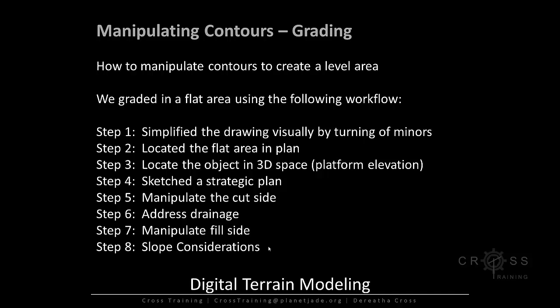So we went through and calculated some of the slope, and we found that the area where we really wanted to place our building was just too steep, and we had to put in a lot of retaining walls. And we found another area that was probably more suitable because it was flatter than the area we were trying to put our building. But this was a good learning exercise, and you don't want to make the same mistake that I made, so hopefully this presentation will help you to remember that when locating something that you need to grade in that's flat, you'll find an area of your site that is already flat, if you can.